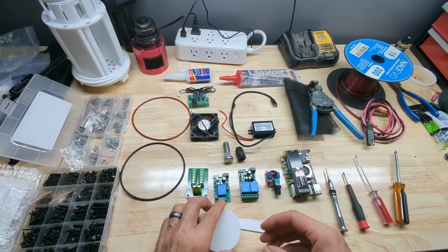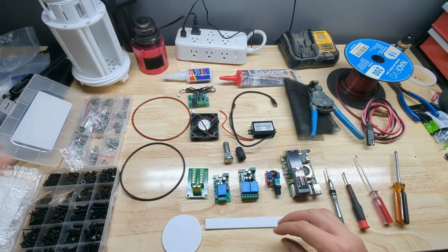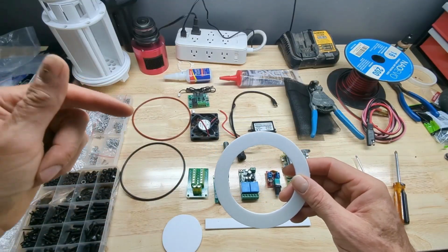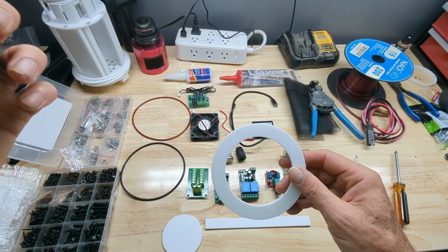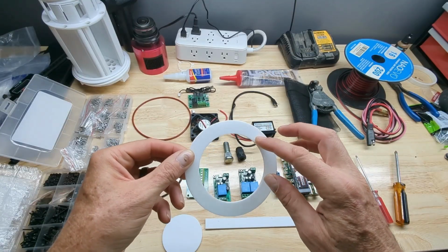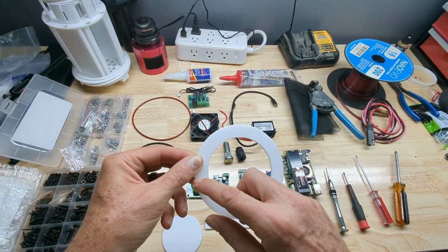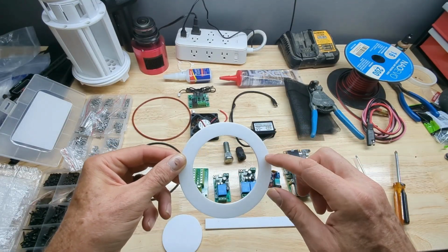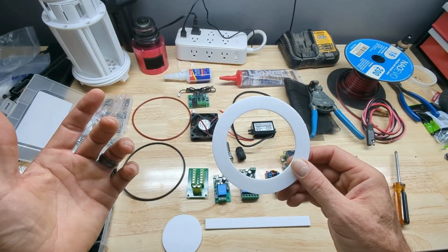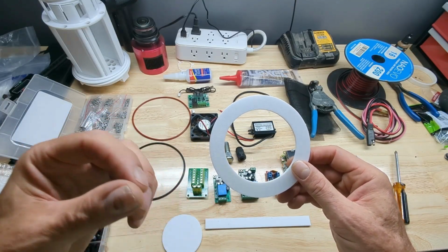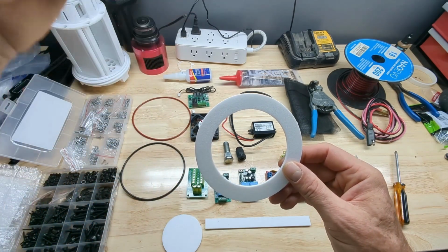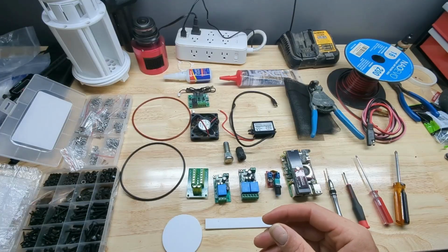And there's also a stencil for if you're printing the standard tube. The vents on it have the same vent ports on the neck that the tall enclosure has, but on the bottom, the ports are actually around the edges like this. And that system is really designed for a chimney effect, where it's a passive heat transfer. So as it warms up inside, air will pull through it and move itself up to the top. Hopefully that makes sense.